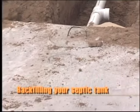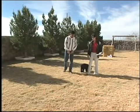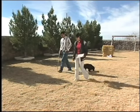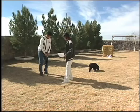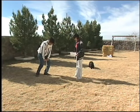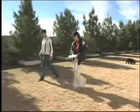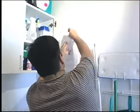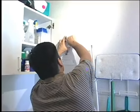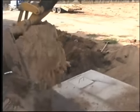But before you backfill, allow for easy long-term access to your tank for future inspection and maintenance. The septic tank location is often a critical piece of information that is lost with time. Proper installation and marking of access ports can save a lot of headaches in the years to come. It is also wise to tape a septic tank location map to the inside of the master bedroom closet. Backfill the soil over the tank to a height of 6 inches to allow for settling and to divert surface